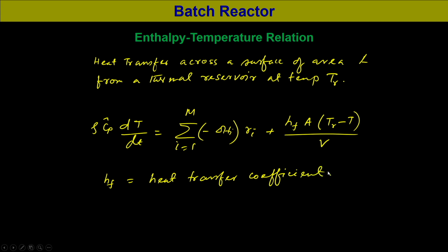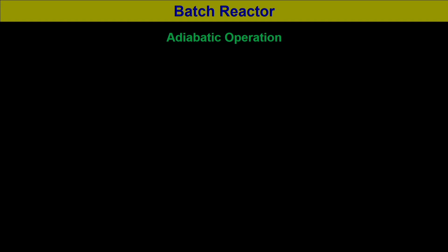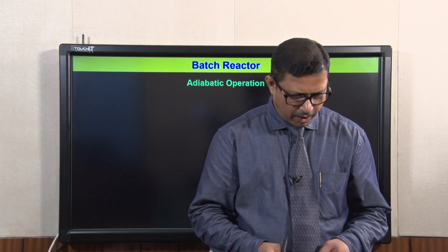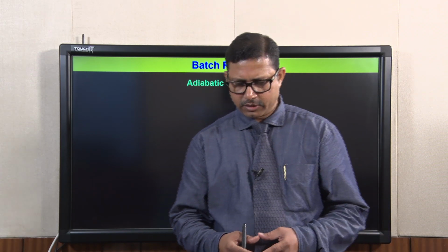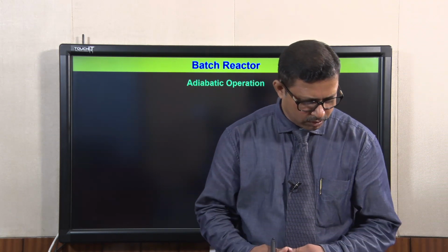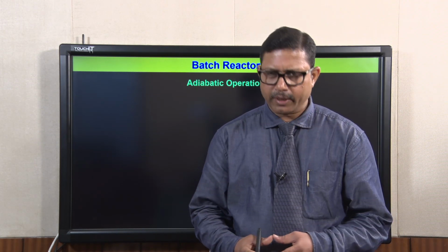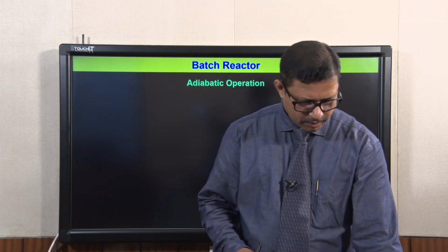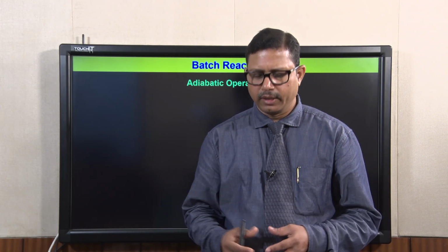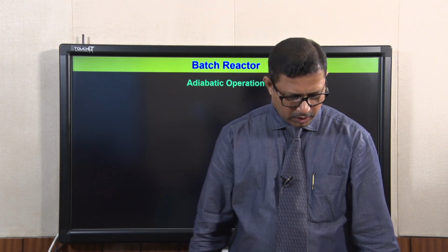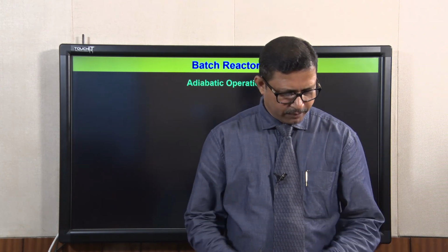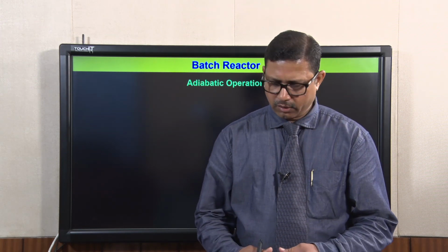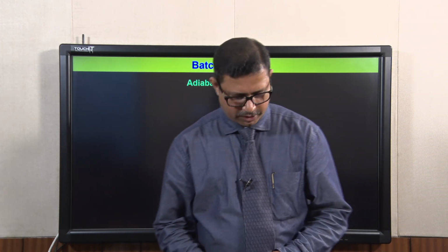So, most of the reactors are non-isothermal reactors, and this is the important case which we need to consider, because for adiabatic reactor, when there is no heat in or heat out, the adiabatic operation is often desirable, because there are few utilities we need to incorporate, and it should be very easy to operate during its normal operation.